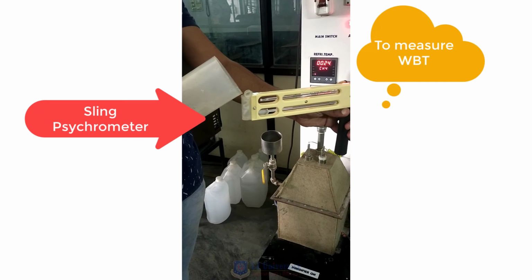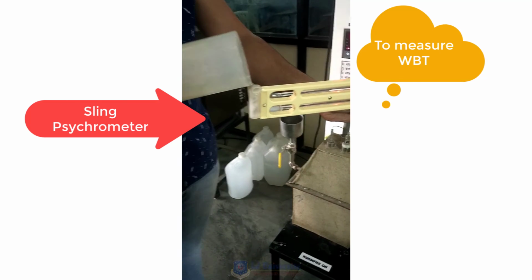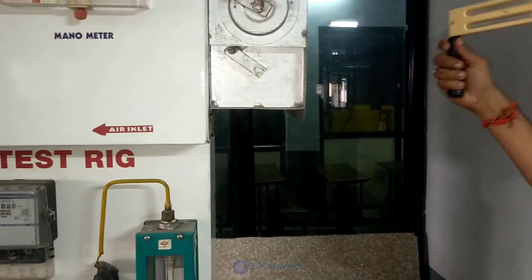After some time we can take readings of the wet bulb temperature, WBT, and dry bulb temperature, DBT, with the help of a sling psychrometer. By using this psychrometer we can measure the WBT and DBT of the inlet condition as well as the outlet condition.